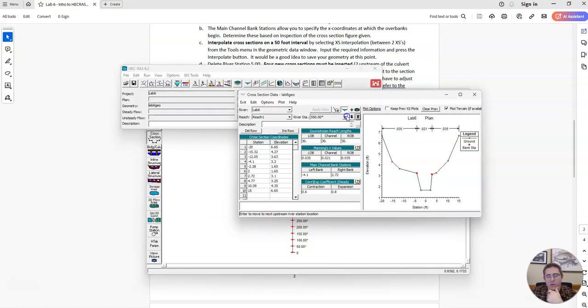So what we did is we moved 550 to 520 and 516, and we moved 450 to 468 and 484, but those are all at the same elevation right now. And what we want is we want them to lie on the same slope that we established initially. But since we just copied them, the actual cross-section itself didn't shift down when we copied it to a new river station.